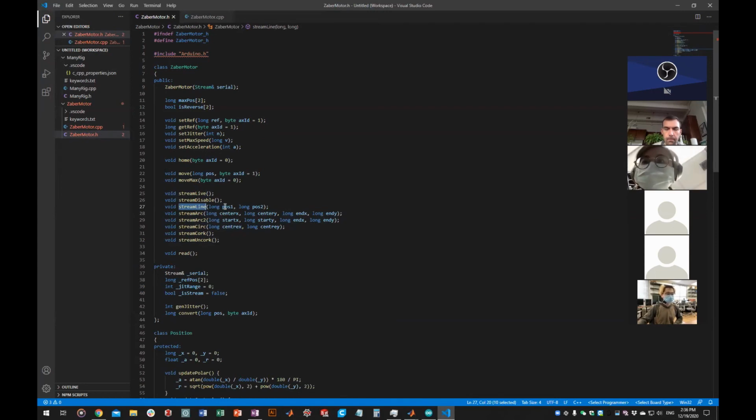If you want to go obliquely, and the distance for the first axis to travel is greater than for the second axis, then the Zaber controller will decrease the speed for the second motor so that the first and second arrive at the destination at the same time. And the vector sum of the speed matches the acceleration and the speed settings here.